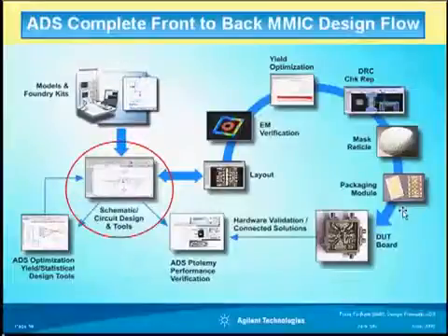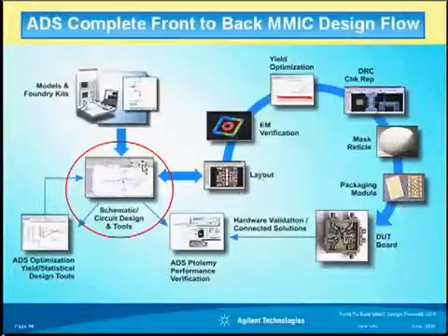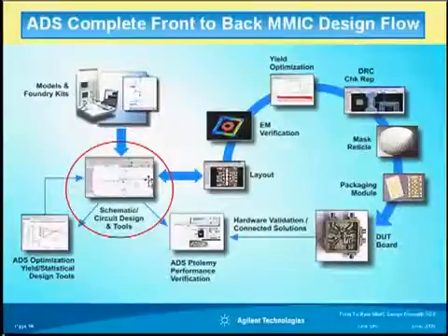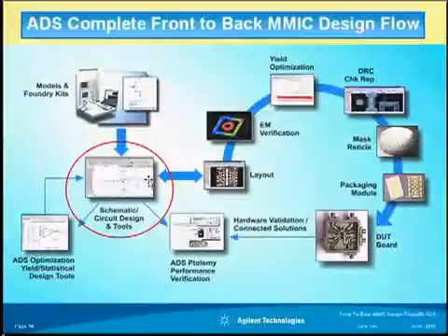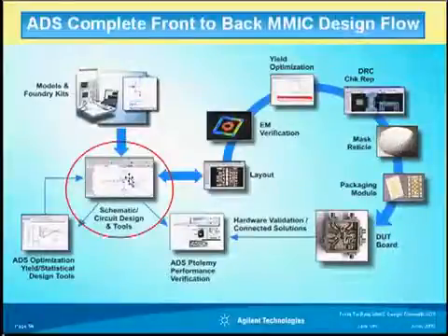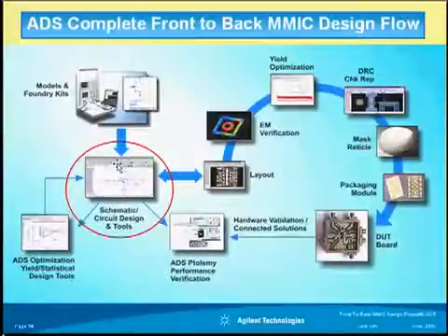After having found a good design kit and models, now the next step is to start our design using the schematic entry along with the various advanced circuit simulators, such as ADS nonlinear harmonic balance, circuit envelope simulator, transient and convolution simulators, linear and system simulators, and planar and 3D EM simulators, all integrated together in a single design environment. So let us show how this step is done in ADS.